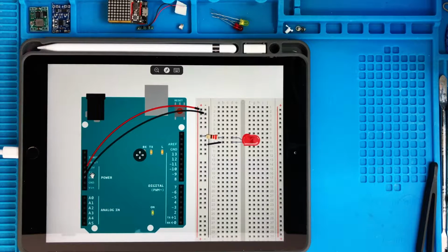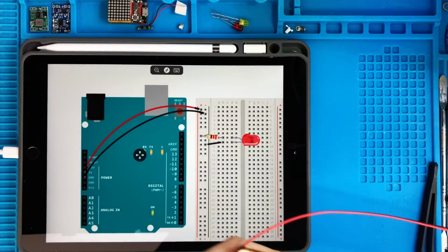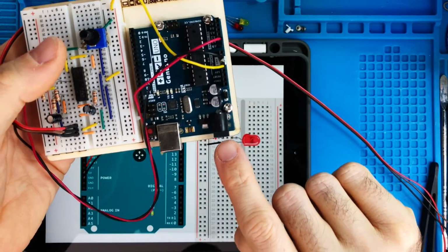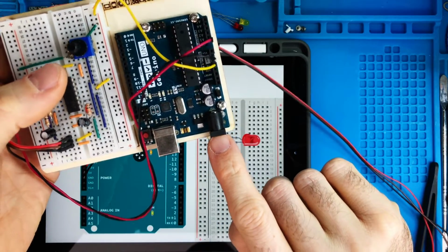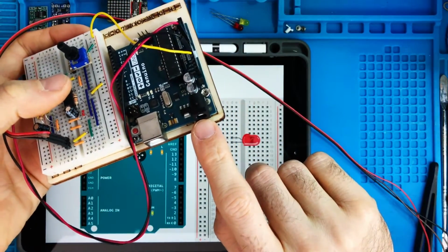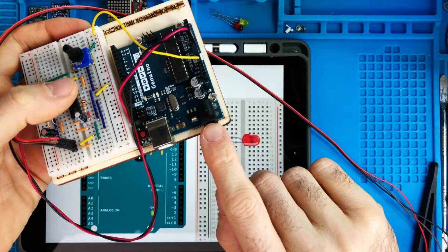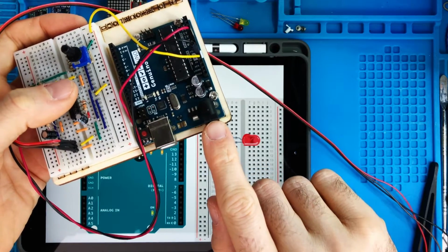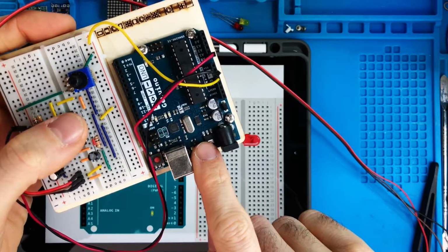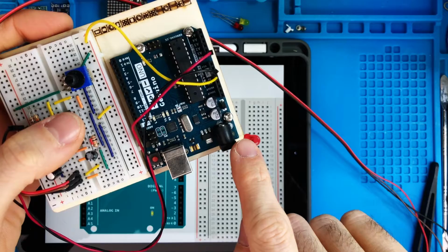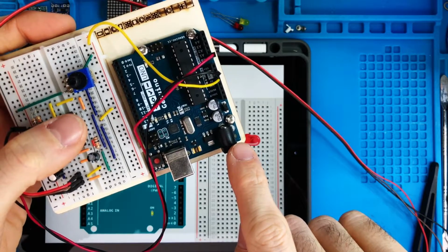Arduino has a voltage regulator that takes the voltage from this outlet here, and you can connect something between 7 to 12 volts here, for instance the 9-volt battery, and then this microchip here will create 5 volts out of this unregulated voltage source.